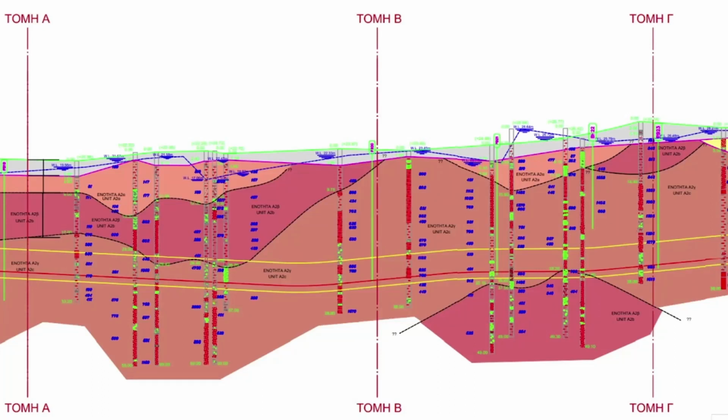The parameters that are varied in the analysis of the sections are the stratigraphy, the geotechnical soil characteristics, the depth of the underground aquifer, the depth of the tunnels, and the existence of the structures above the tunnels. The analysis aimed to investigate the ground surface stresses and, in a second stage, the tunnel and the overlying structures, in each case studying the results in terms of displacements.